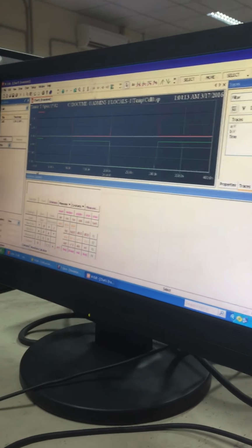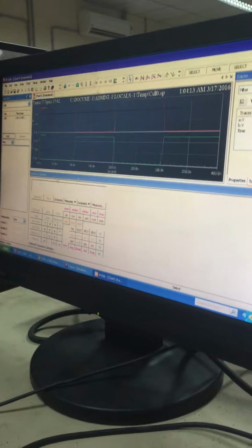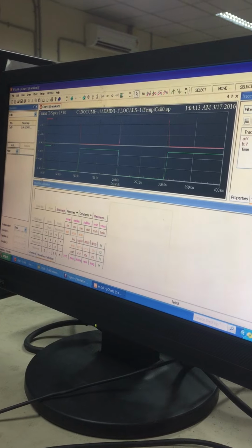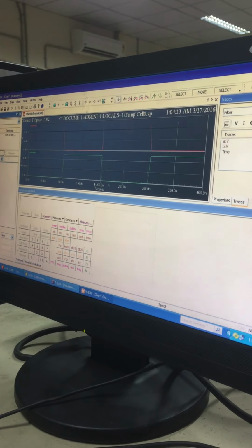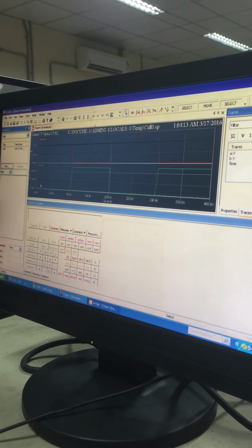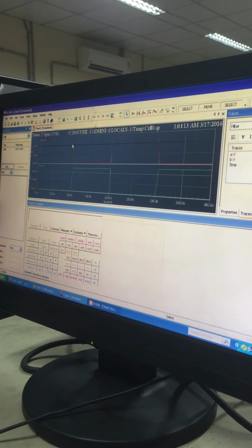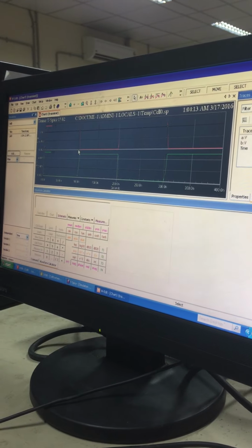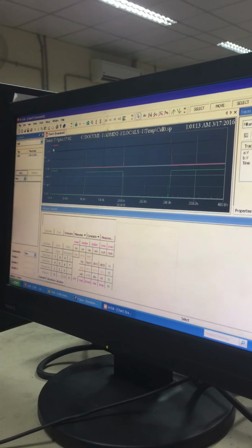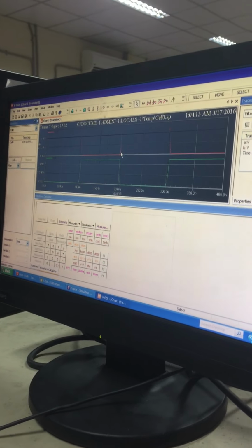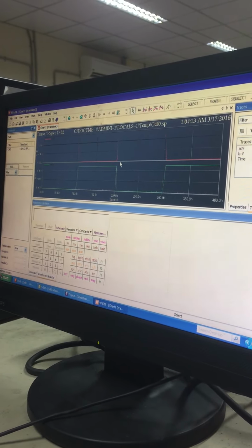இதான் அவுட்புட். ஸோ அந்த ட்ரான்ஸியன்ட் டைம் 0 to 400 கொடுத்துருந்தேன் நான். So for total duration, simulation time is for 400 nanoseconds, and each pulse duration is of 100. So you're getting four pulse durations in that period, 400. And this is rise time, and this is fall time. And there it was given 95 to 100. From here till here it is 100, இல்லையா? From here till here it is 100. So 5n வந்து the rise time போயிடுச்சு. So 95n is defined there, and total duration is still 200. So one on time and one off time, total is 200.